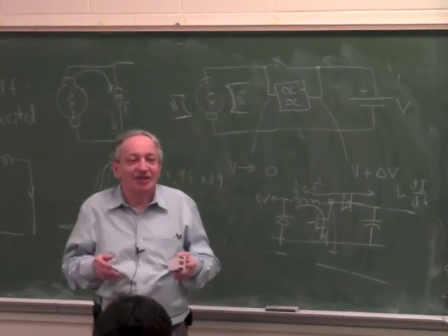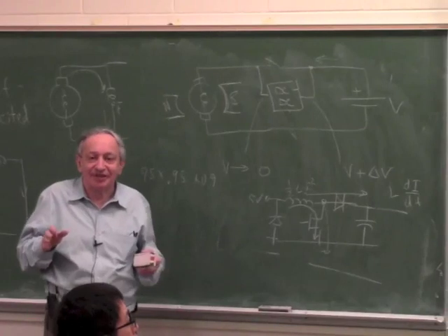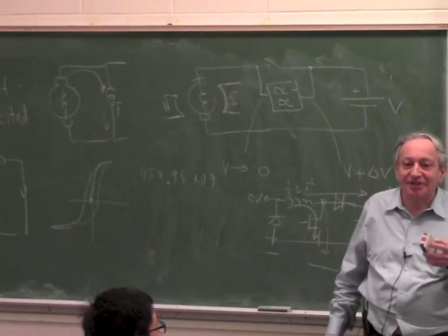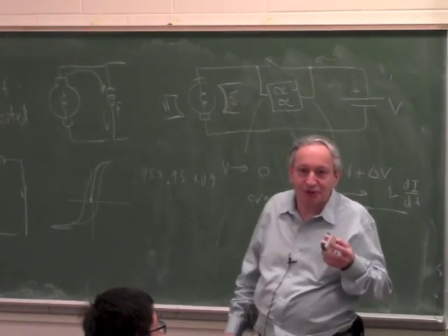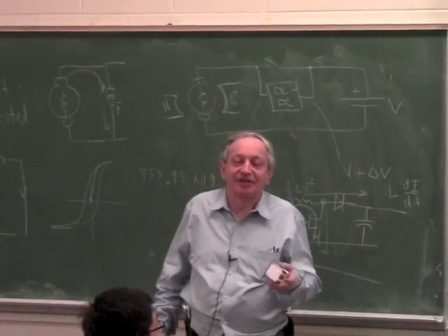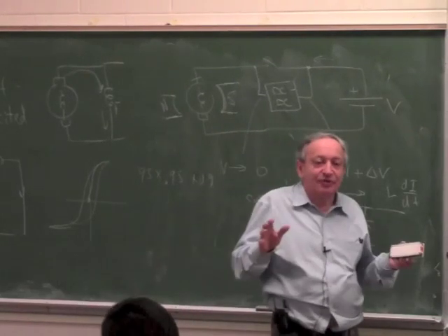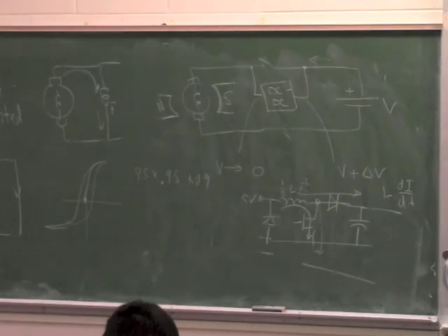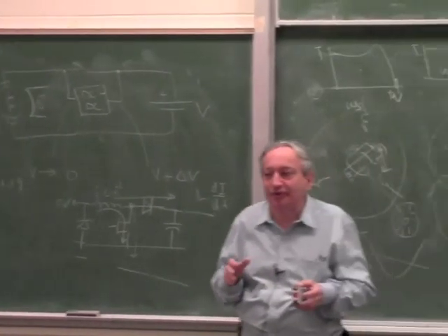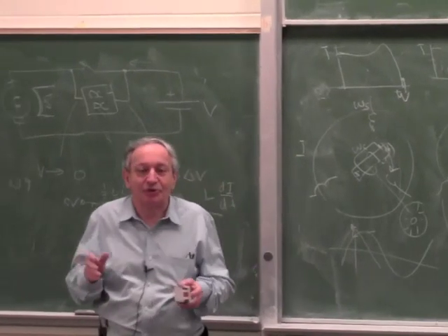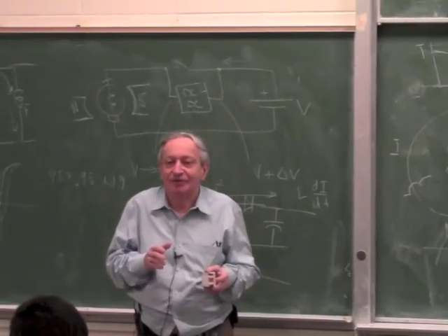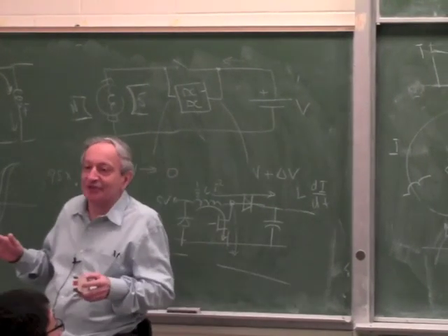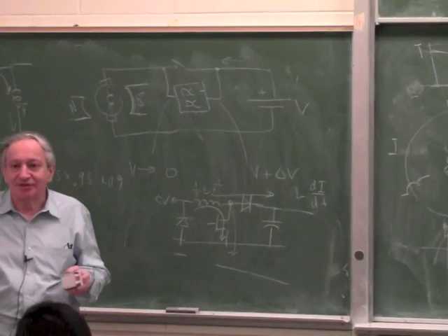Basically, for any other servo system which is not electric, if you understand how an electrical servo system works, you can easily make the conversion. You have to remember that what's called current in an electric servo is called flow in a fluidic servo, and what's called voltage in an electric servo is called pressure in a fluidic servo. So now you can use the same equations.